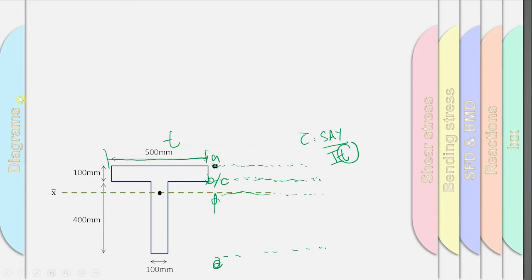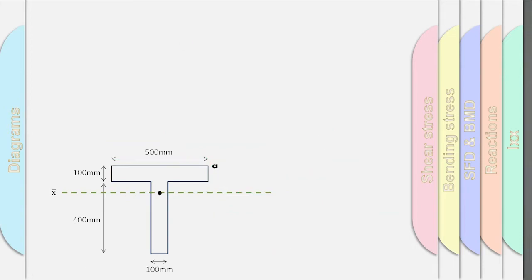So we do the shear stress for the first point, which is point A. For point A, the formula is there, and it is zero. There is no area, as I taught you before; there is no area above point A. Point A is at that particular place, so there is no beam area above A. So the area is zero, and when there is no area, there is no Y, since there is no distance from the centroid of the area above A to the centroid of the whole section.